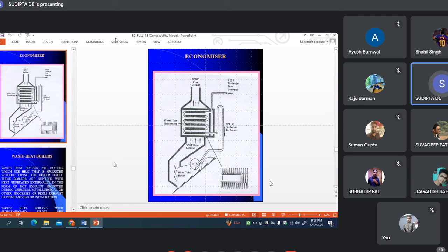What is the boiler installation? If I visualize the proper water heating process, initially there is sensible liquid heating up to saturation temperature, then a constant temperature evaporation process, and then superheating. So in the heating of these three phases, the corresponding equipment is also different. Superheating has to be done separately in a superheater in the highest temperature section of the boiler.